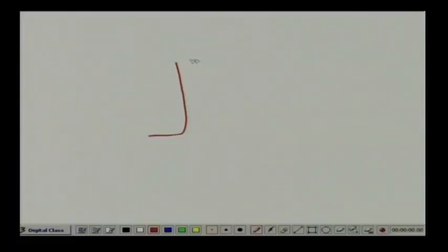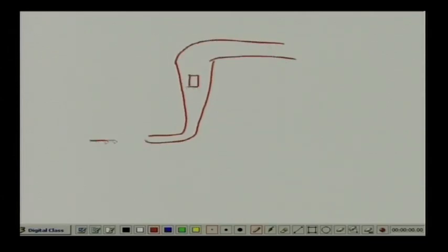Other applications of LVDT: we have seen the rotameter in many places. So, we have a channel like this, and the float is here. The flow is in this direction, coming out in this direction. With a grommet sealing, they connect a core here, with two secondaries in opposition.